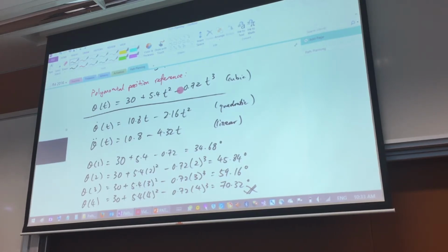Now what you have seen is a linkage that didn't really talk about the acceleration profile yet. So if I were to add two more boundary conditions, by saying initially it would have a certain acceleration, and as it reaches the end position, it has another acceleration as well. So altogether, I'll give you 6 boundary conditions. 6 boundary conditions, how many order? 5th order. So we're going to solve that.